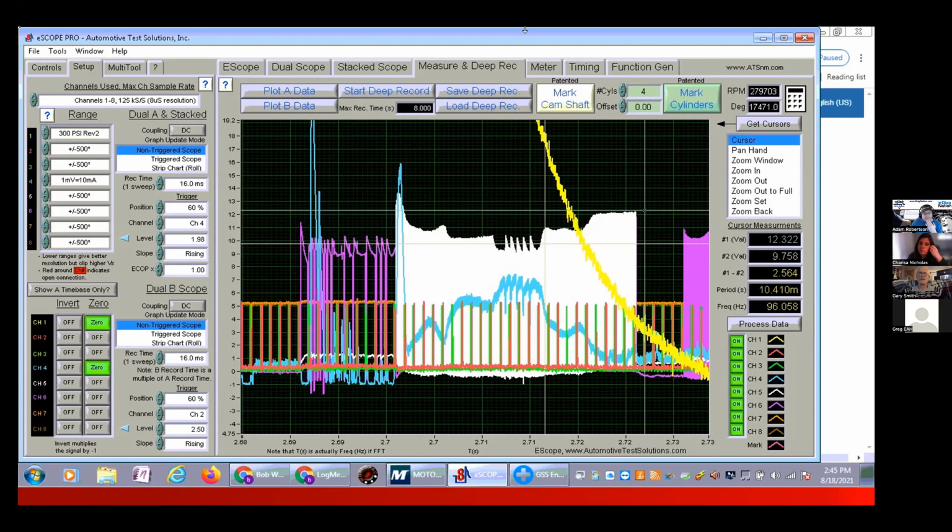Yeah, specifically, Greg, that's a function of the H bridge, okay? Which is the driver chip. But in the case of an H bridge, when it's driving AC or when it's driving inductive AC in a BLDC, I should say, the flip-flop between above the ground line and below the ground line becomes the issue, which is why you didn't see what you expected to see.